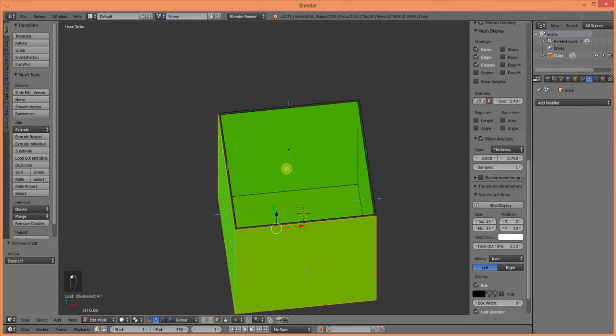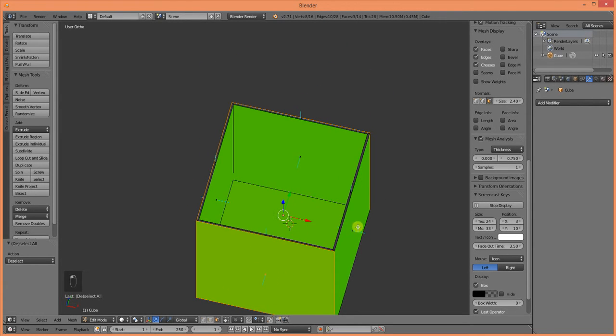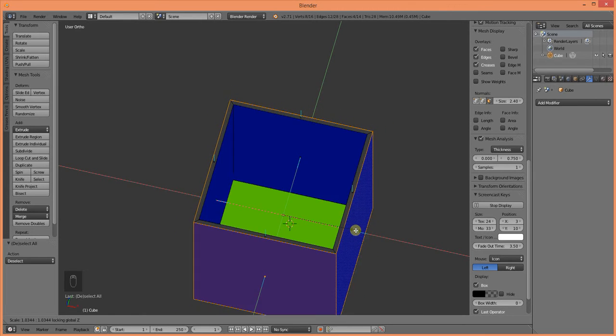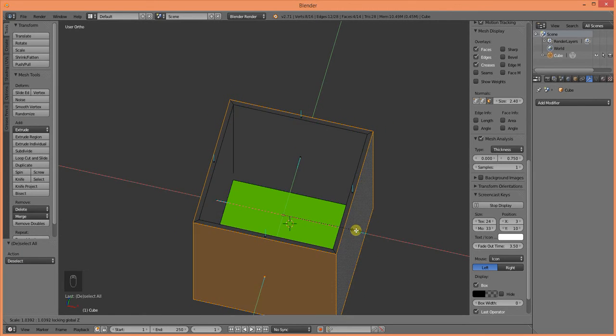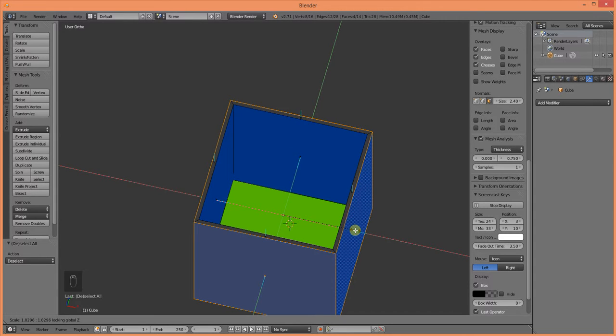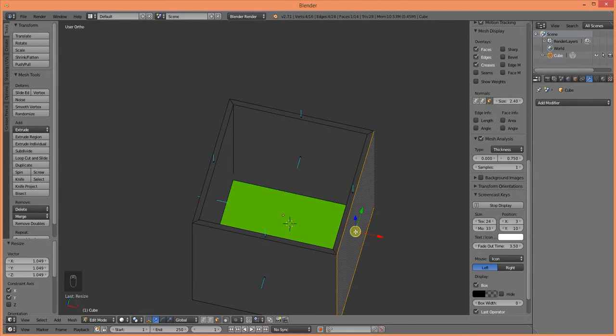So let's go ahead and select our outside edges or outside faces. Scale in all directions, but see, as I'm scaling it up, the color is changing. So it's becoming a cooler and cooler color, saying that I'm getting within tolerance. And then whenever the color disappears, I'm within tolerance on that.